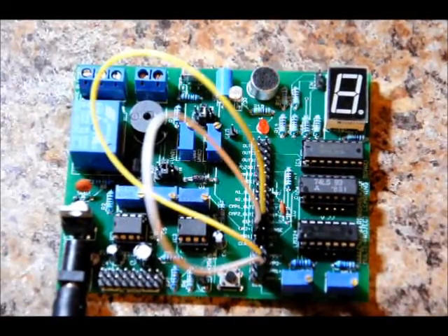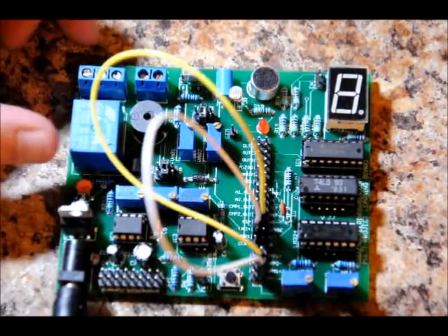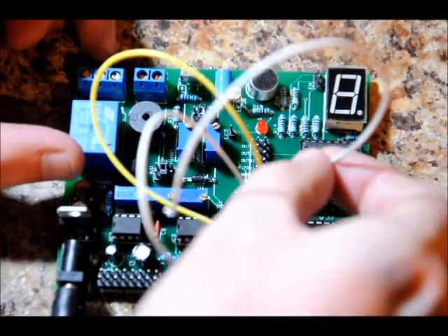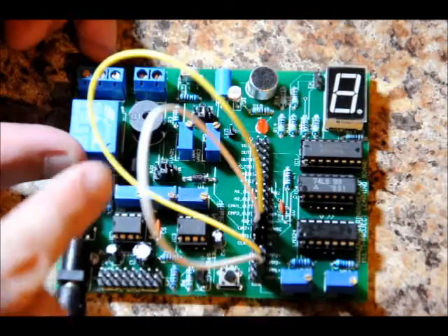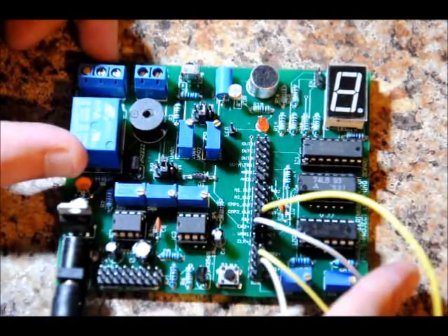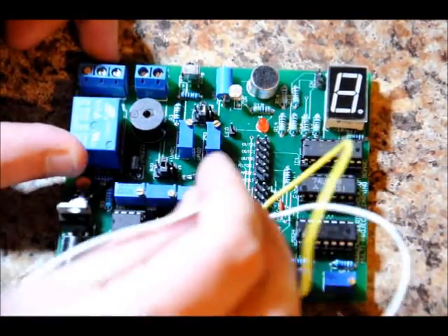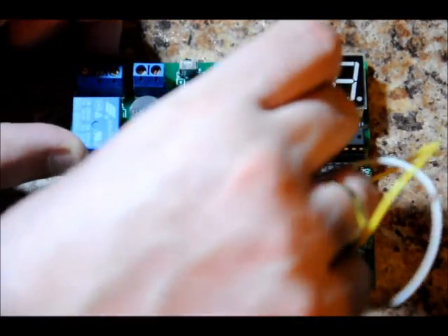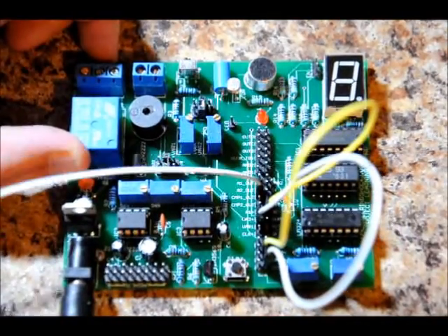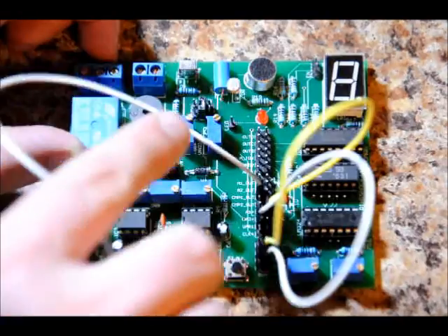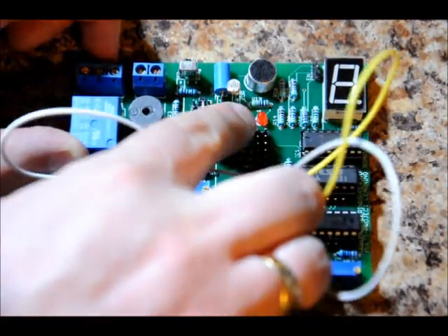Lastly, what we want to do is place our comparator output on our LED block. There is a line here at the bottom labeled CMP1 out. Comparator out. Comparator 2 out is right below, but we're not using comparator 2. And our LED block is right here. That's our LED.